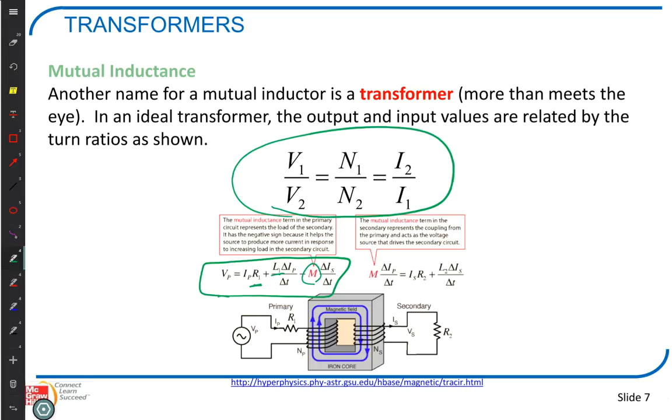When there's high demand, they actually lower the voltage that comes out of the plugs, because that's lowering the power that you're going to use so that they can supply electricity to more people, and you don't notice really the difference. Most people don't realize that. So the actual voltage coming out depends on where you are and when you measure it. So we're somewhere between 110 and 120, and in Malaysia, somewhere between 220 and 240.